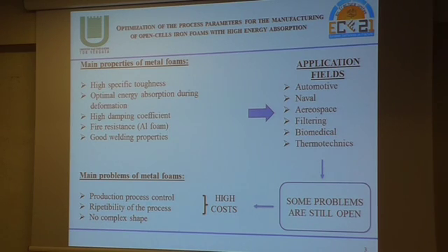Main properties of metal foams: high specific toughness, optimal energy absorption during deformation in compressive test, high damping coefficient, and fire resistance for aluminum foam, but at the same time also good welding properties. For all these reasons, main application fields are transportation, automotive, naval, aerospace, in which lightness is important for the structure, but also filtering, biomedical applications, or thermotechnics.